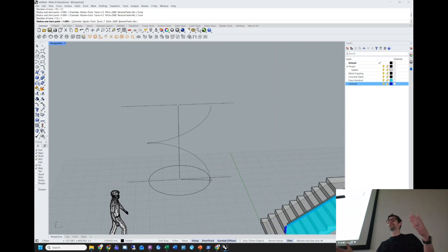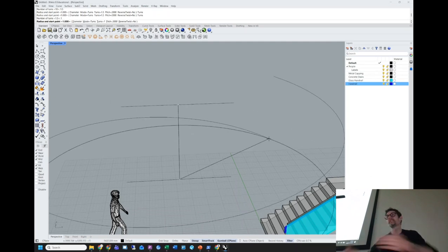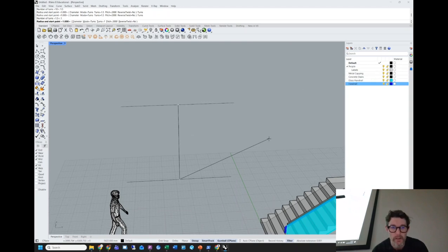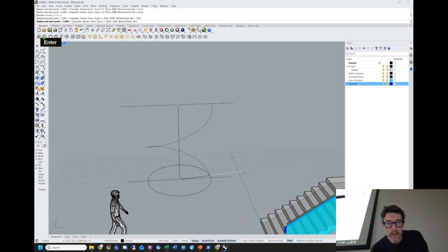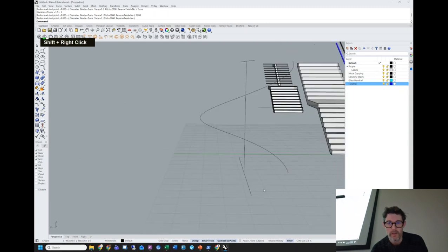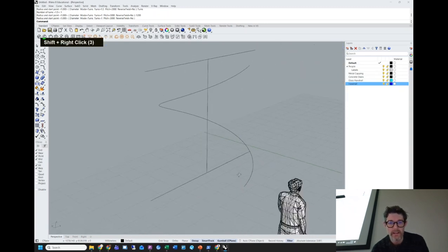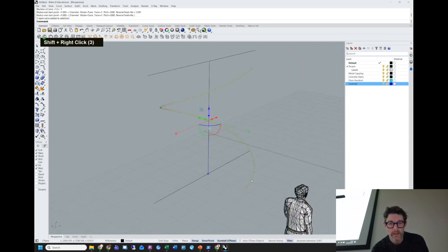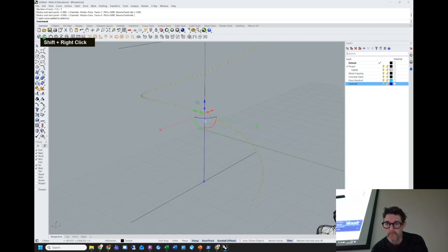So I need this to be a fairly decent amount of space, because the bit in the middle is going to be a super, super small slice of cheese. And the bit at the end, the stairs are going to be really, really deep. So people aren't going to want to walk there. So actually, I might want to make that something like 1200 radius. And now I've set that in place, and now I can just choose the direction I want my staircase to go in, and I'll click there once. There we go. So now I've got the outline of my helix, my spiral staircase.